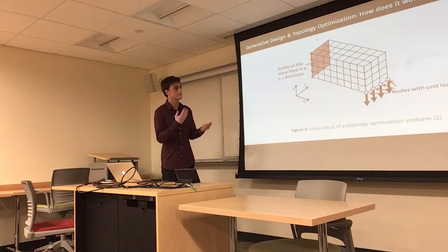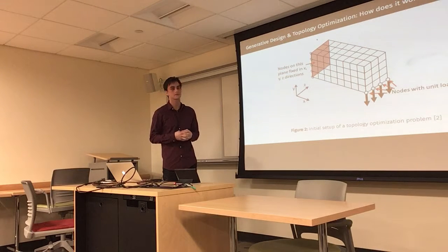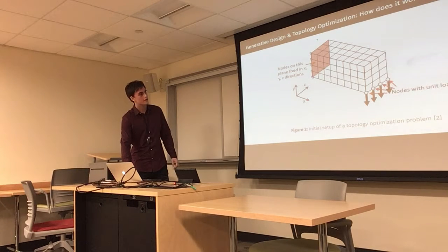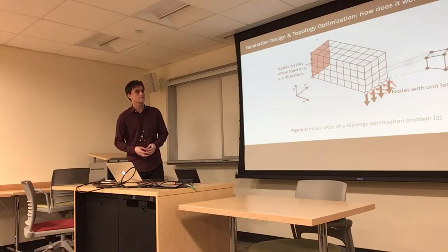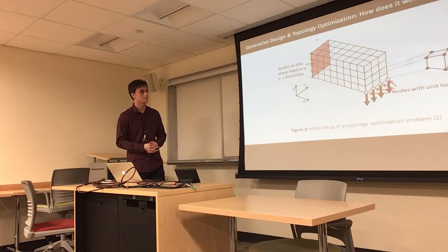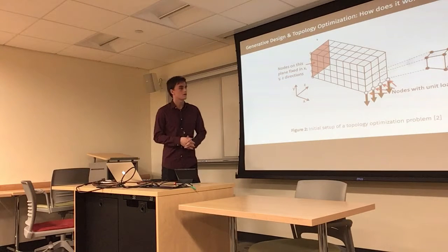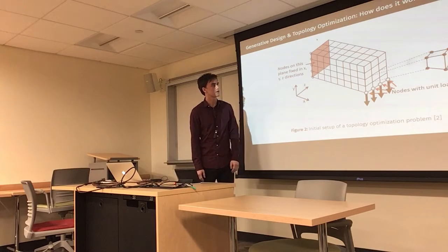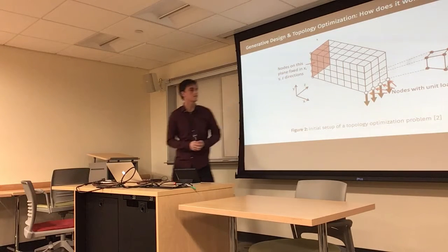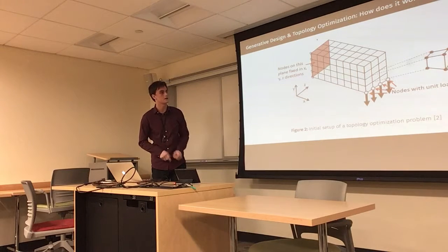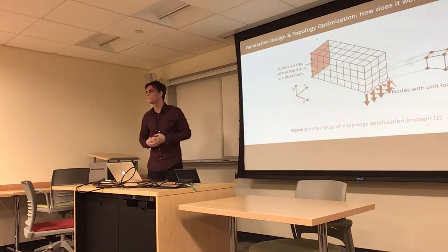we can define a system that's composed of these cubes. And these cubes ultimately have 8 nodes and 6 faces. So these just represent a small volumetric volume of the entire design. And when we place certain constraints, we put this initial system attached to a wall on the back end, and we also attach some surface loads in a uniform fashion at the end of this cantilever beam.